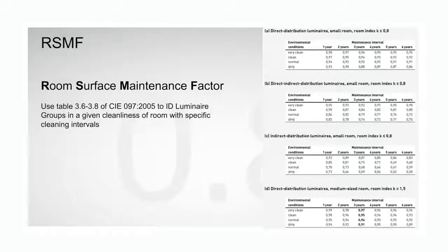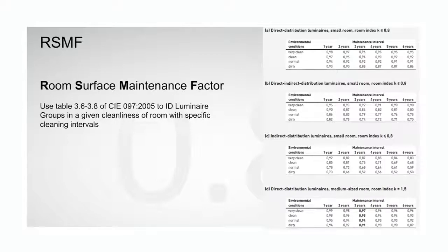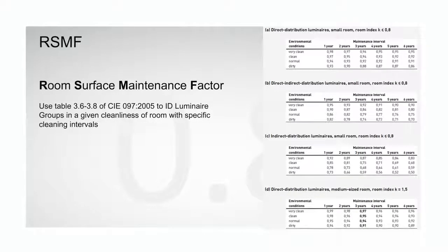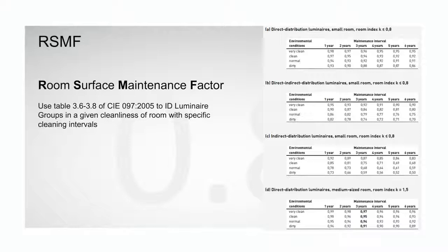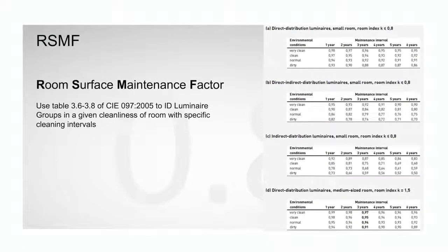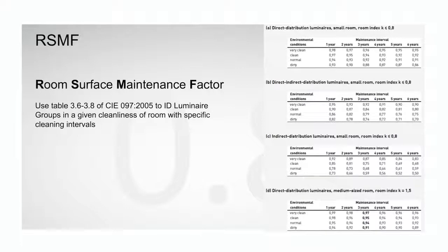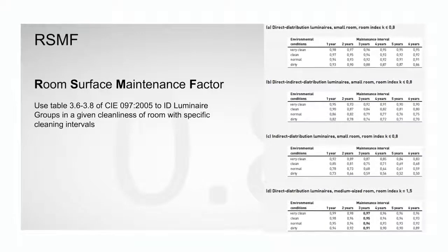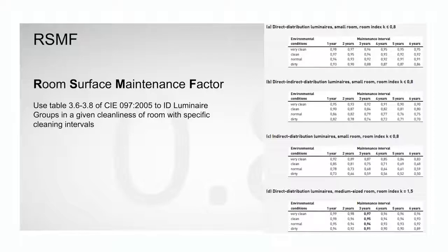Yes. And room surface maintenance factor, this is the final one on the CIE lookup tables. So this gives you a list of room dirtiness levels, from clean through to very clean through to very dirty, and then maintenance levels. So you look at the maintenance that is going to be put in by the client as to how often they're going to be cleaned. And again, this is another area where I think there's been a lot of misleading information where people have constantly put in, oh, the luminaire is going to be cleaned every 2 or 3 years.